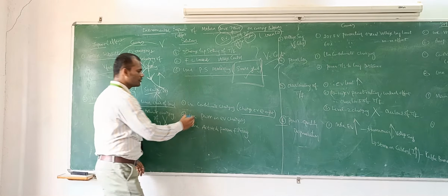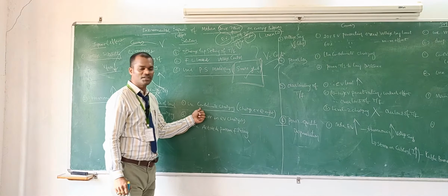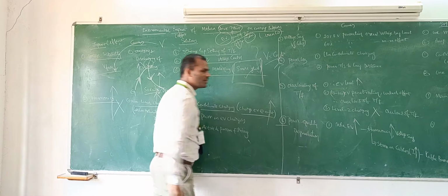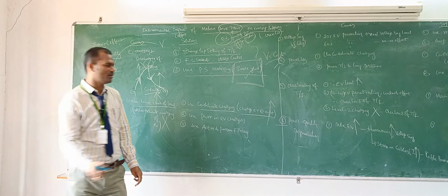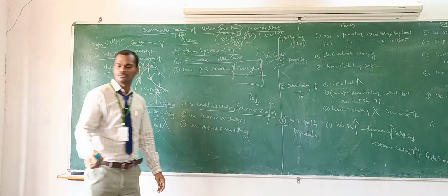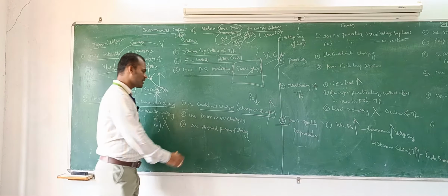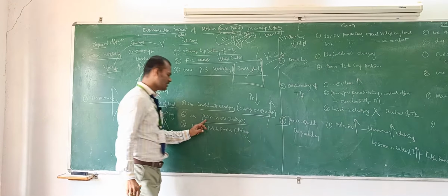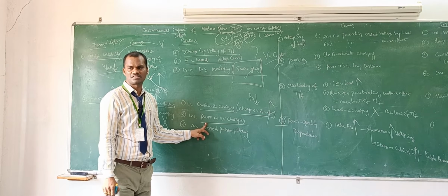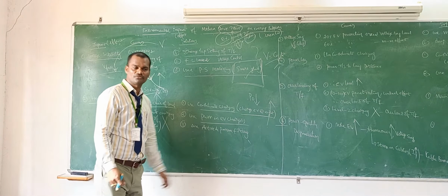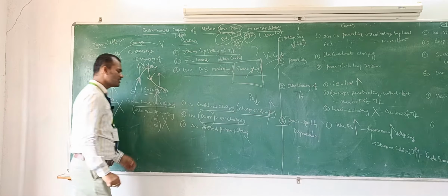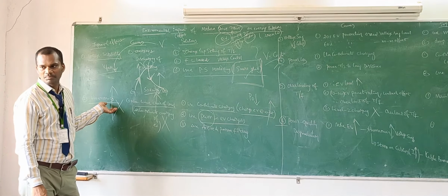Okay, which type of charging method should you use? Coordinated charging method, and you charge your electric vehicle only at low peak hours, when you have low load demand. When you have low load demand at night time, then you can charge your electric vehicle. Next one, use a charger which consists of pulse width modulation. We have AC chargers and DC chargers. We have to use the latest chargers which consist of pulse width modulation. Automatically the harmonics can be eliminated.